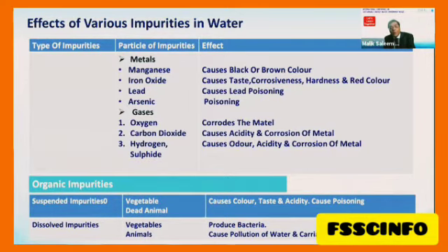And they don't provide any water analysis. Actually, sometimes you don't need RO plants. Sometimes you need an ultrafiltration plant. Sometimes you need iron removal or arsenic removal or selective ion removal.